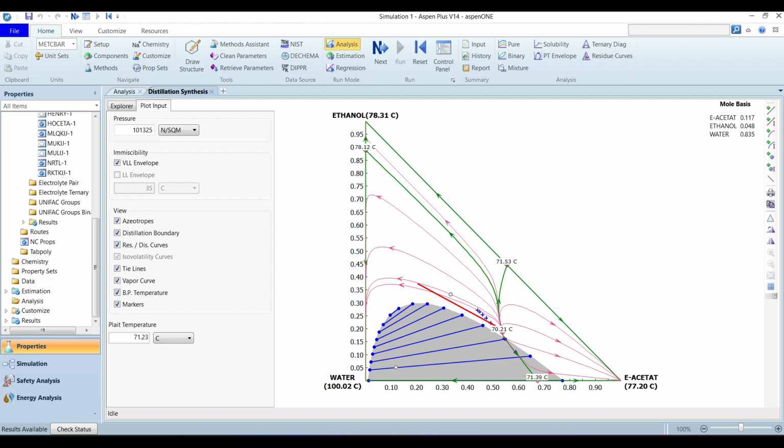So let's say we add some water and we land on this two-phase liquid-liquid region, and we can do the liquid-liquid extraction. We just give some residence time and take one product from the bottom phase and one product from the upper phase, and the compositions of the two liquid-liquid products should be exactly on this tie line. You can drop a straight line as a tie line. So one product will be on the right of this envelope and one on the left of the envelope.